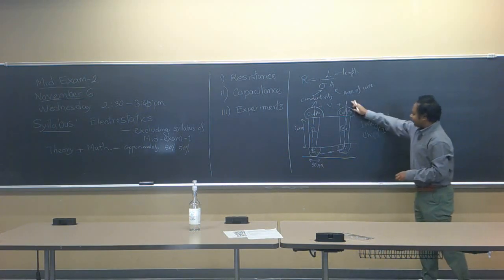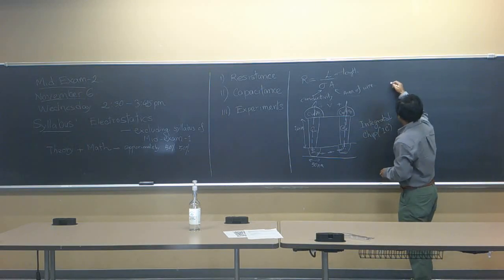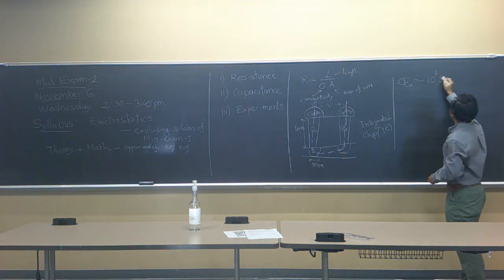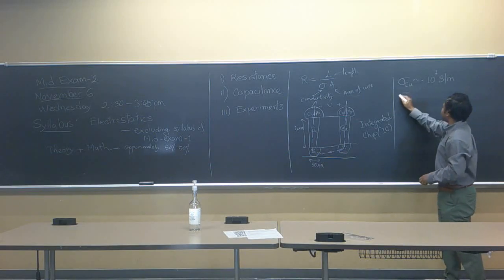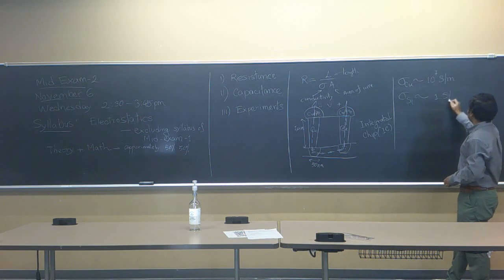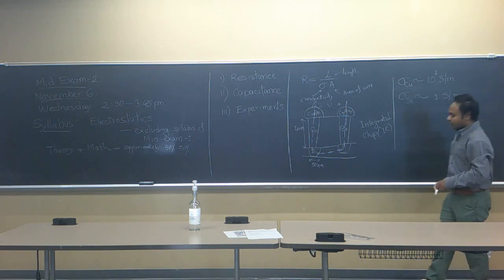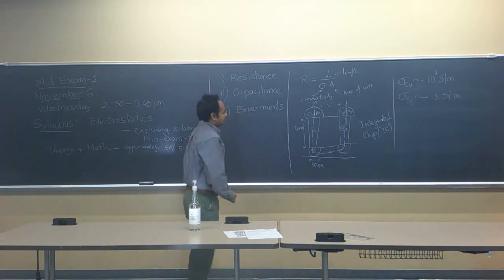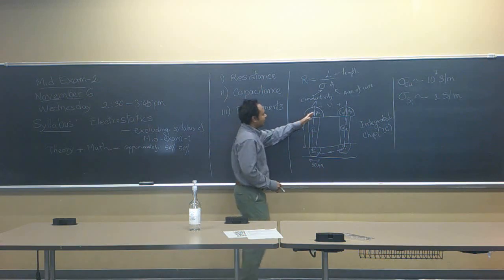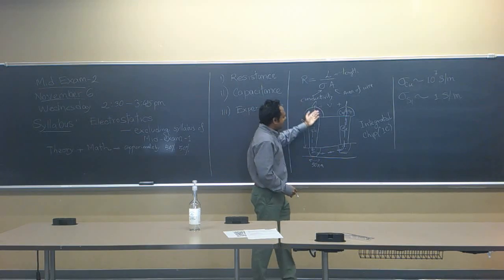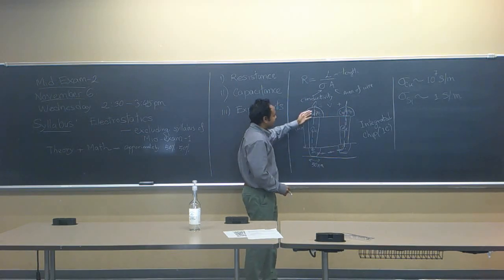In the case of an IC where we have copper wire, the copper has a high conductivity, up to 10 to the power 7 Siemens per meter, and the silicon device has a very moderate conductivity, just 1 or 2 Siemens per meter. So in order to have your resistance as minimum as possible, how are you going to design this IC?